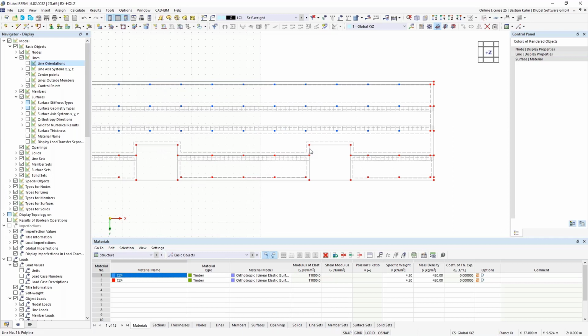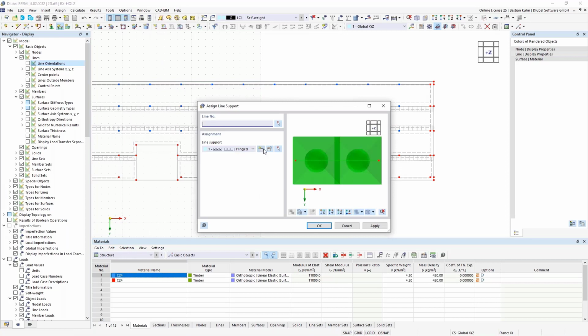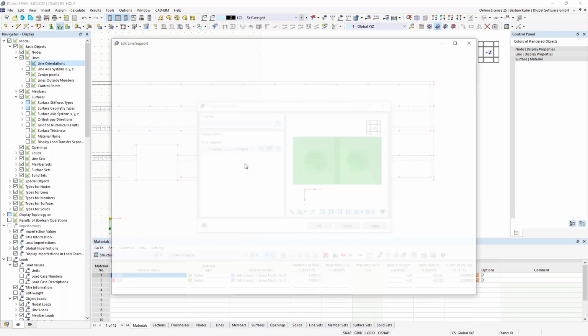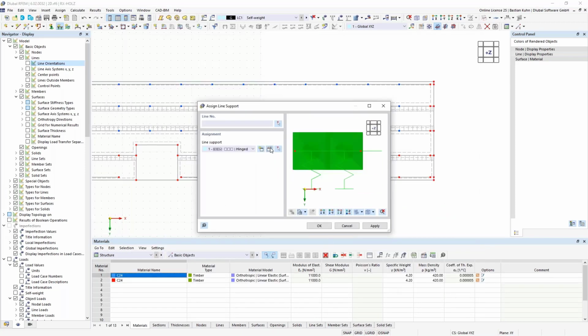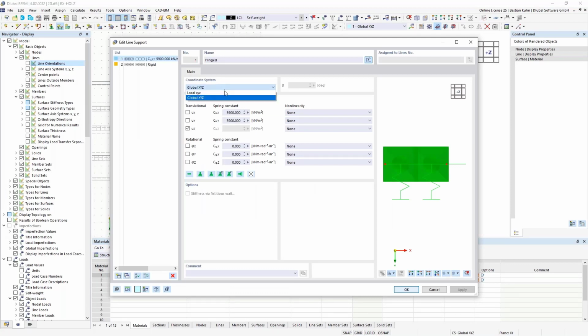for the 3D building, we also need this line hinges, but for the 2D building, we do not need that. And there we will define line supports, but the line supports have actually the same stiffness than the line hinges have. So I define it here in the same way. And of course, I want the support in that direction. That's something what we sure want. Hold on, I made a small mistake. And the coordinate system should be oriented in local direction.